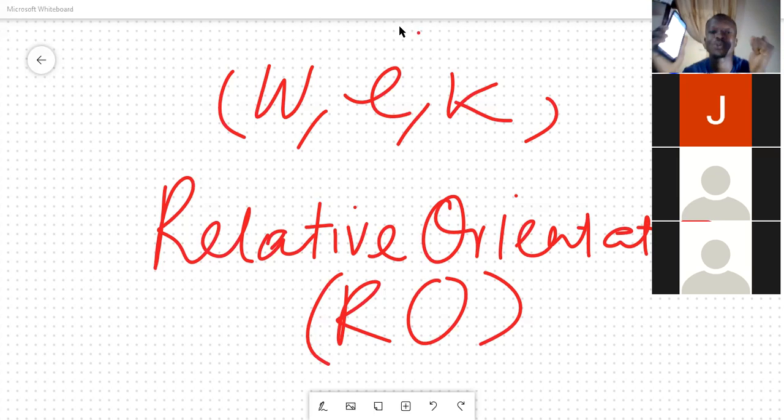Okay, so we can actually bring the two together. Also, let's not forget that we are interested in keeping the projectors vertical. We are dealing with vertical photography, so we want to keep the orientation of the projectors in such a way that we have the model formed. So relative orientation is about that.